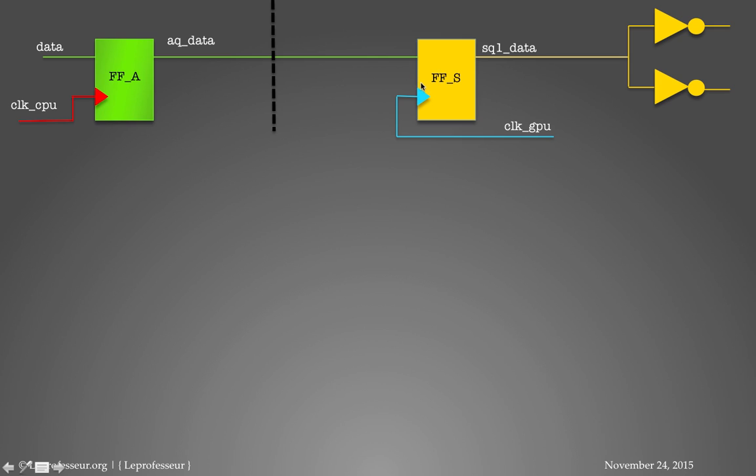So we have to enforce that requirement. For example, let's say this is my clock, and this is the clock edge, the rising edge. Every flip-flop has a requirement that your data signal should be stable before the rising edge of the clock.